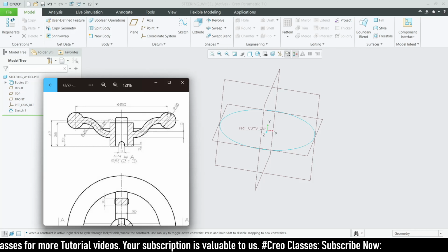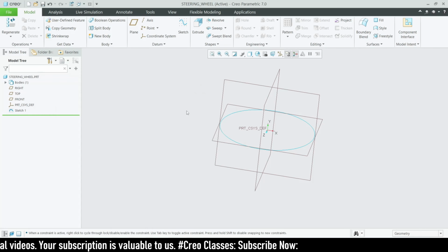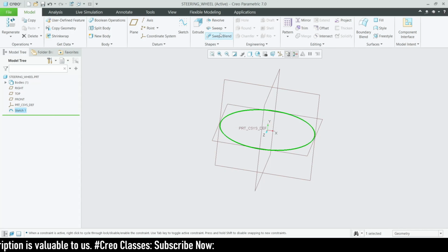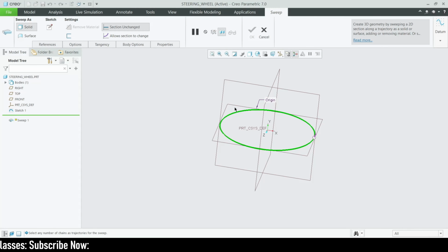Okay, so at first I'm going to draw the circle by using the sweep tool. This circle dia will be 26. So at first I'm going to select this sketch which we have done before, and I am going for the normal sweep. We don't want to use helical sweep here. As you can see, the entire circle has been selected, as this will be our origin point because there is only one point where the point gets started and it will end at the same point.